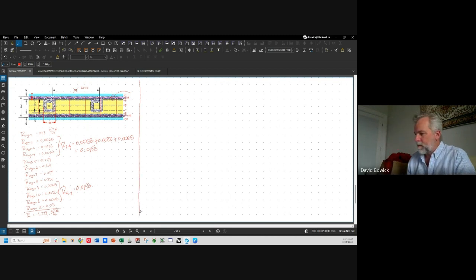Now, the next thing to do is define our design condition. Indoor temperature and humidity: T indoor equals 24 degrees Celsius and H equals 50%. This is our indoor design case.